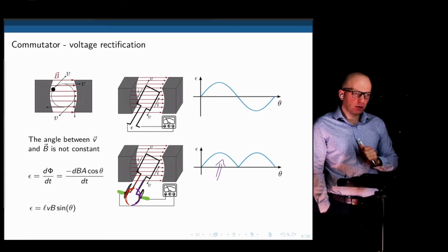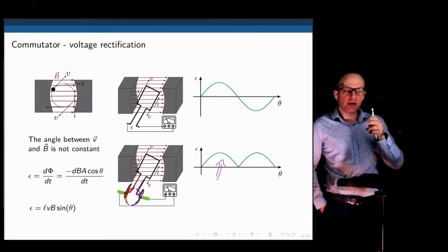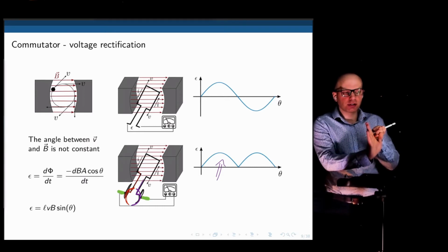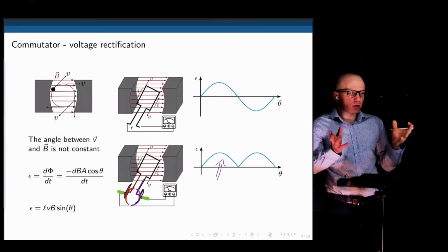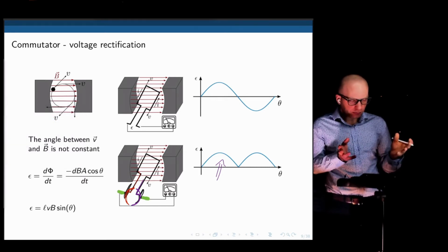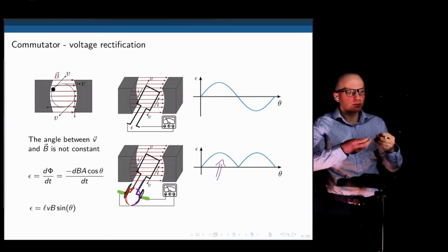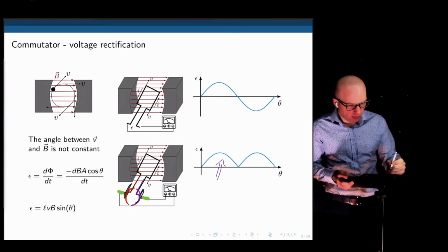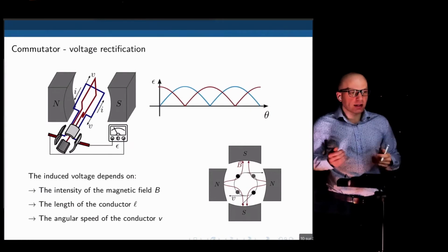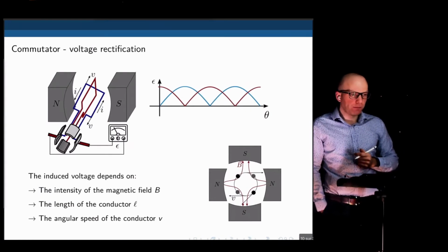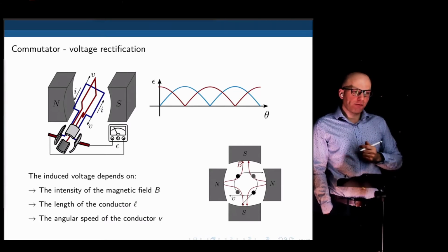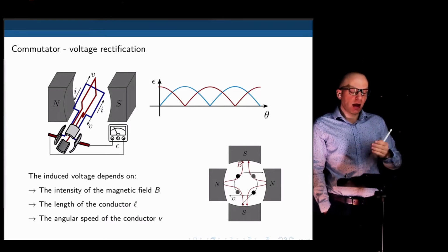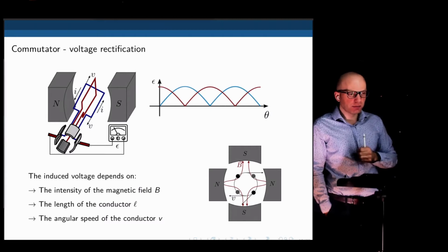How could we add a phase shift? We can add another coil, and make that coil shifted with respect to the first one. There are points in this system where the coil doesn't produce any back EMF, so there is no point in keeping contact with the coil when it doesn't produce any back EMF. So we add a second coil here that is, in this case, 90 degrees out of phase with respect to the first. And now it has its own commutators as well.